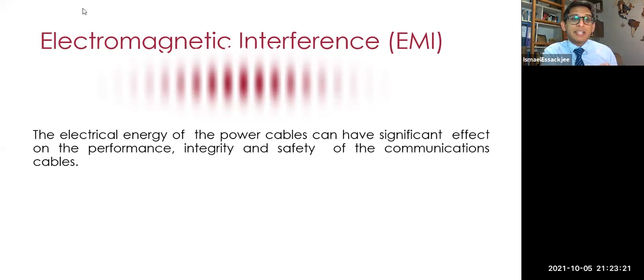Noise is going to affect the integrity. Maybe 1, 0 becomes 0, 1, whatever. Or it can cause some malfunction, some noise in the system, as we say. Or safety. Why safety? If you are putting your power cable very close to the communication cable, the power cable, remember, is going to heat up because it's carrying huge current, not huge, but design current. And when current is passing through a cable, it's going to heat up. This is normal, inherent. So your network cable is next to it. It's going to heat your network. The network cable has not been designed to sustain heat.